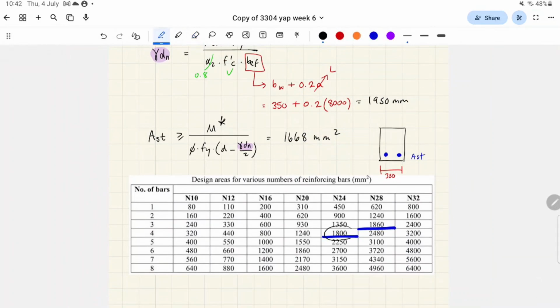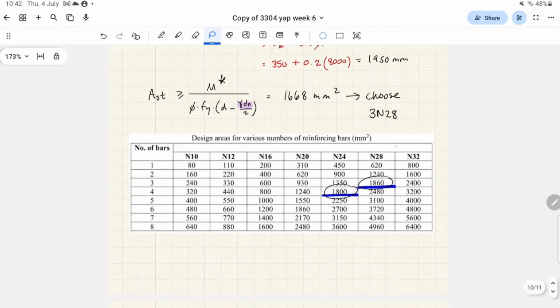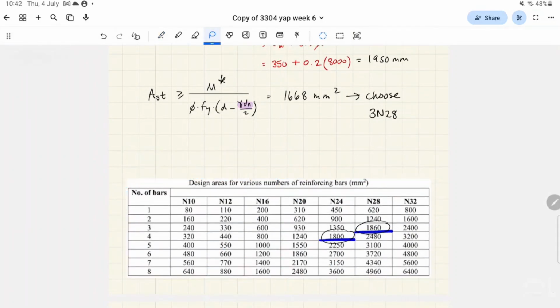Anyway, I would say your answer, Josh, is good. The answer they provide though is they choose two N28s. Sorry, that was a big tangent, but have you got something out of that? So in the case that they've chosen the N28, as you said, it's a lot heavier, per bar. But since there's 3 bars, N28 in reality would not be the most optimal. Is that what you're trying to say? Oh, no, N30. Sorry, N28s are relatively okay to handle. N32s is where it starts getting a bit difficult to install.